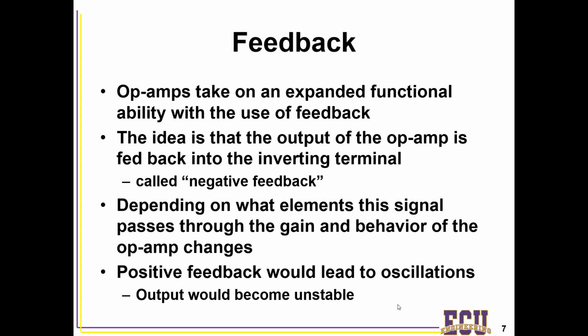So feedback is very important. Feedback takes on the functionality of actually taking the output from the amplifier and putting it back into the input of the amplifier. This basically allows you to figure out if you are gaining the way you intend to gain. So if you're trying to output, say, an audio signal, feeding back in some of the output audio signal allows you to know, did I get to the gain that I wanted to achieve? Typically, we put this back into the inverting terminal because that is considered the negative on the amplifier. That is called negative feedback. Negative feedback allows us to stabilize our output.